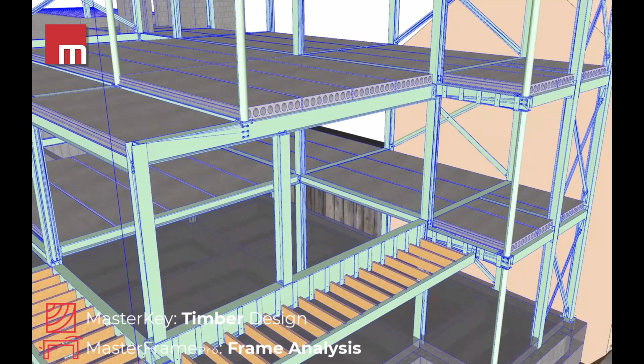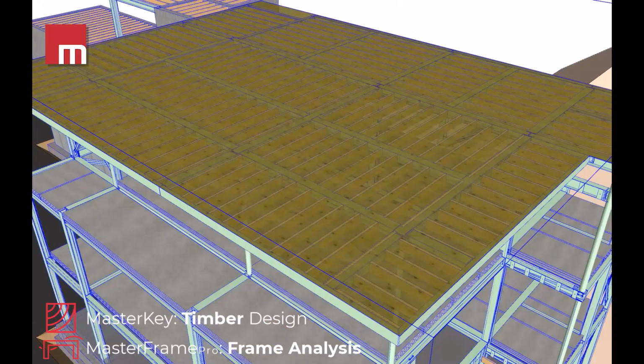With the option of modelling and designing timber joists within MasterFrame, personally I would recommend against modelling all these individual joists throughout. As we can see here, I've actually got a plywood deck sort of covering that as well.